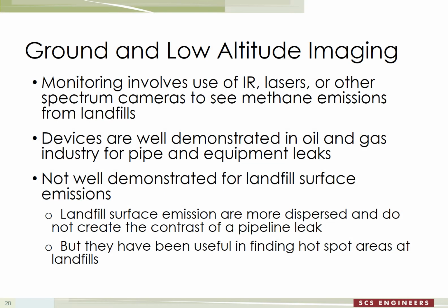So beyond the traditional surface monitoring, we do have some other options, and these involve the use again of imaging: optical imaging, infrared, laser, or other types of spectrum cameras that allow us to see methane emissions from a landfill and to actually measure the concentrations. They are very commonly used in the oil and gas industry for looking at pipe and equipment leaks. Not as much use on the landfill emission side of things, in part because landfill emissions tend to be a little more dispersed, so some techniques don't see them very well, because there's not enough contrast.